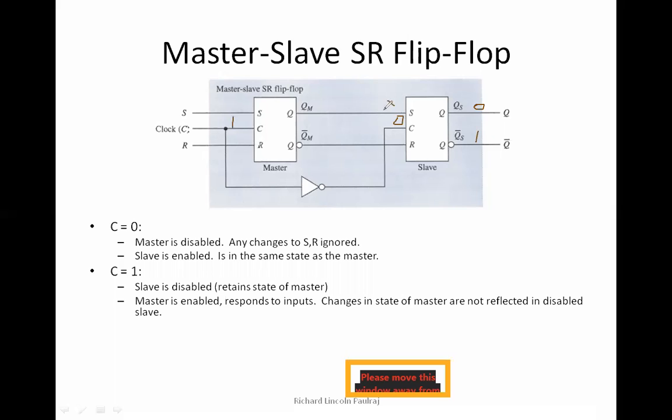Whatever values are at SR will not pass on to the slave. Understood? This is restricting itself from taking inputs because the clock is 0. So that's why I've said it retains the state. Whatever was there previously, that same state will be kept constant.